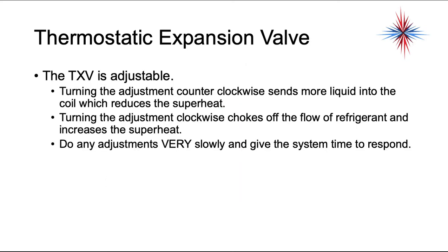The TXV is adjustable. Turning the adjustment counterclockwise sends more liquid into the coil, which reduces the superheat. Turning the adjustment clockwise chokes off the flow of liquid and increases the superheat. You need to do any adjustments very slowly and give the system time to respond.